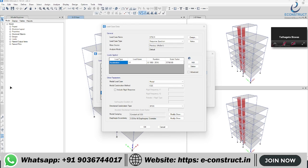Yes. And generally if the entire building is non-orthogonal, that kind of scenario happens in a big structure which is high rise. In a very small structure, you will get that kind of non-orthogonal shape very rarely. Mostly it will be for the facade and such things, they have done that kind of geometry. If that is the case and it is high rise, then earthquake will never govern. It is the wind governing structure. So that time wind tunnel will be coming in.